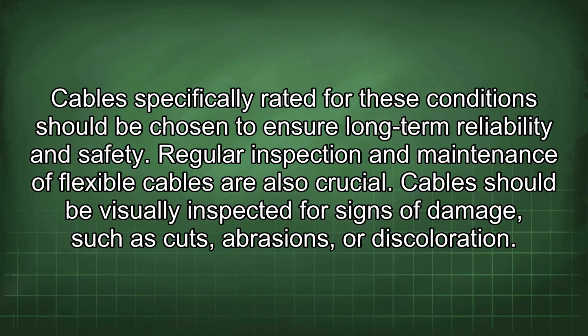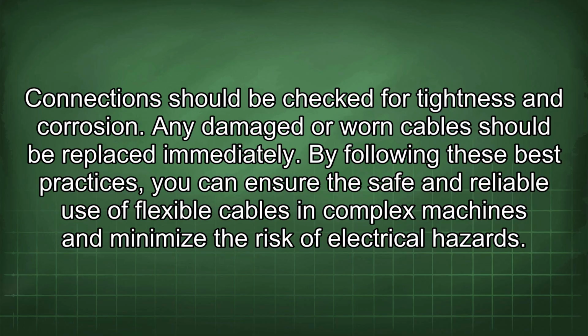Regular inspection and maintenance of flexible cables are also crucial. Cables should be visually inspected for signs of damage such as cuts, abrasions, or discoloration. Connections should be checked for tightness and corrosion. Any damaged or worn cable should be replaced immediately. By following these best practices, you can ensure the safe and reliable use of flexible cables in complex machines and minimize the risk of electrical hazards.